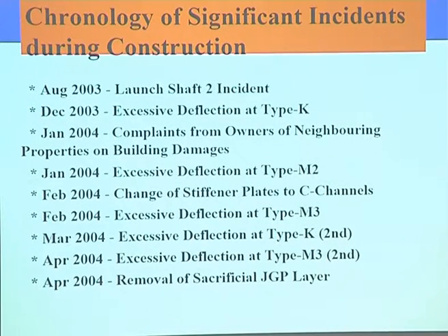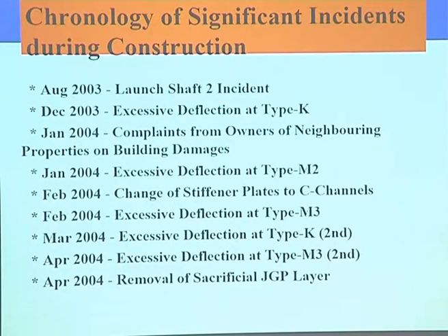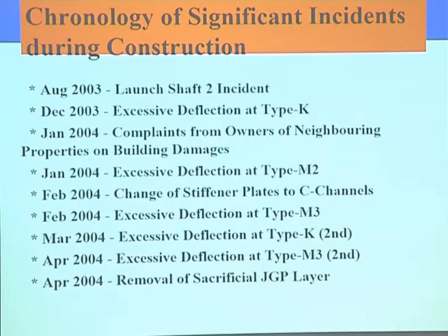Okay, so these are some of the incidents. You see, even before the collapse, there have been a whole string of incidents: excessive deflection, excessive deflection, excessive deflection. When you see a whole string of incidents like that as an engineer, alarm bells must be going off in the mind. But somehow people are still pushing on as though nothing has happened. They were pushing ahead, just making sure that they meet the timing. But actually, the design was all wrong.